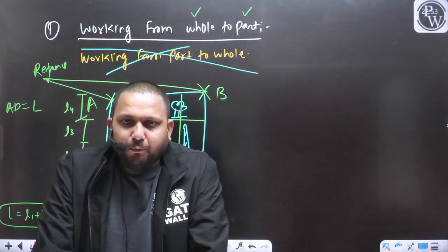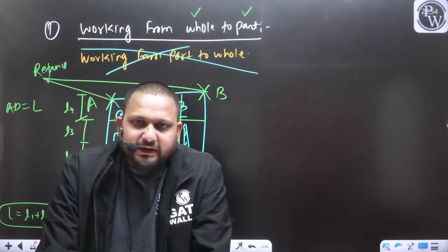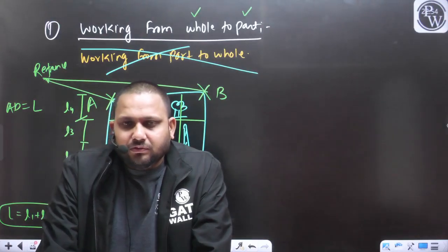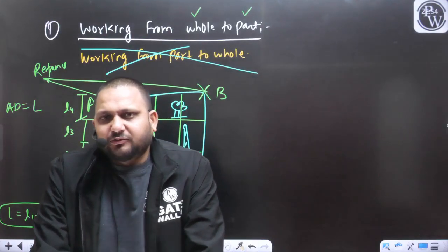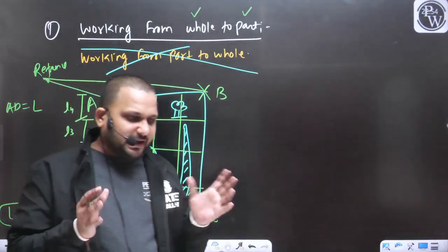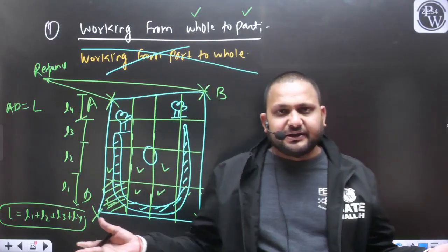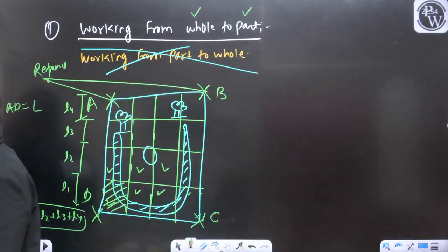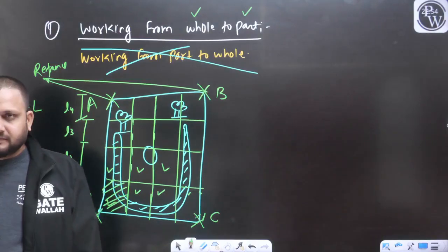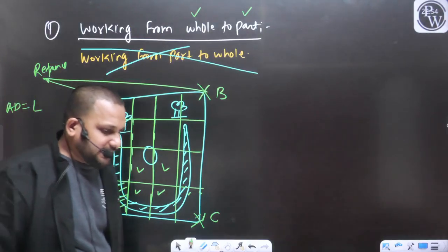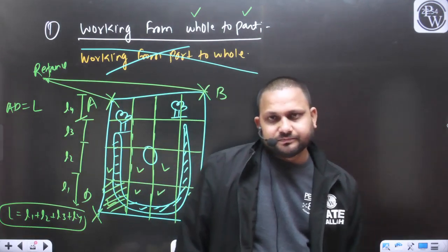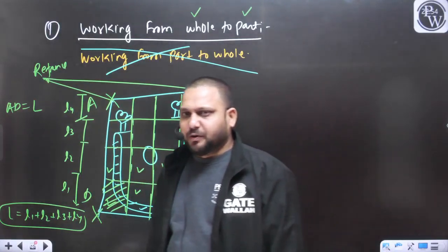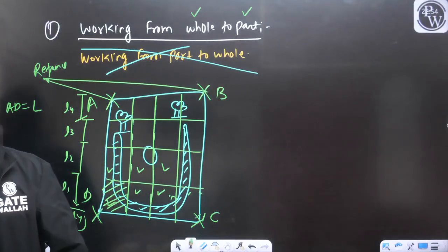If we have defined point A accurately and point D accurately, the summation of all the parts should be equal to capital L. If there is any difference, we can identify the error in our measurement. In this way, if you follow the first principle of surveying, you can prevent the accumulation of error.